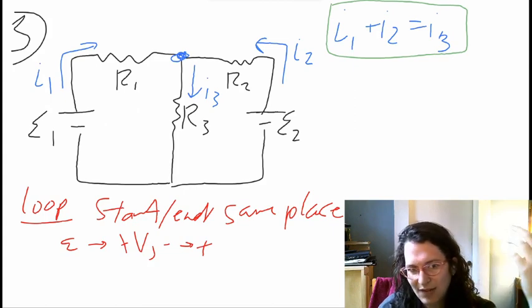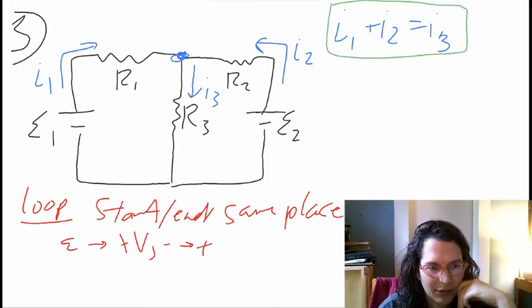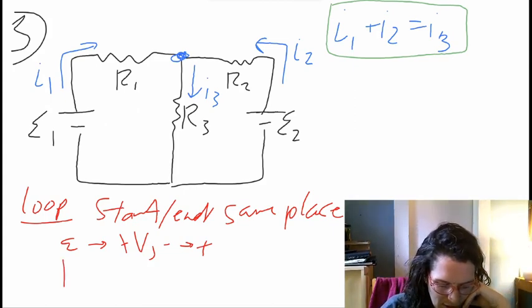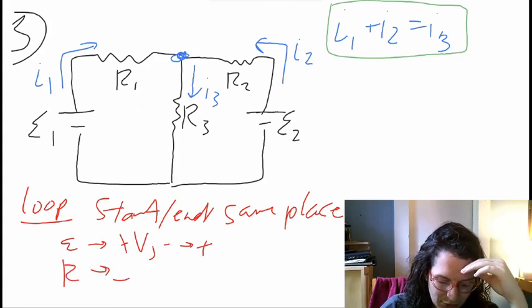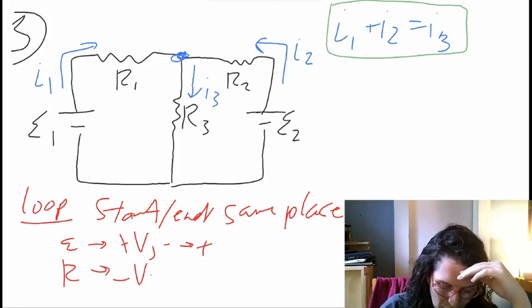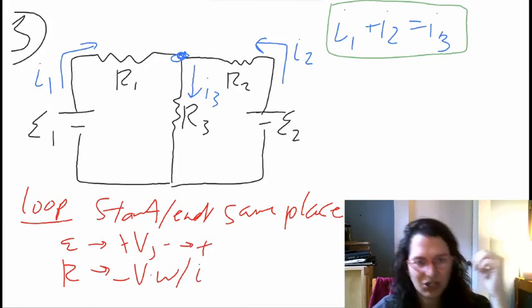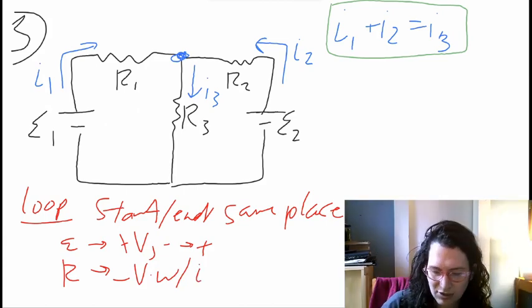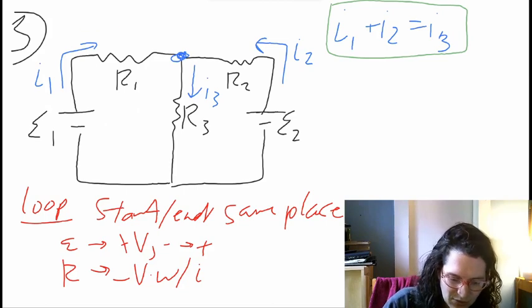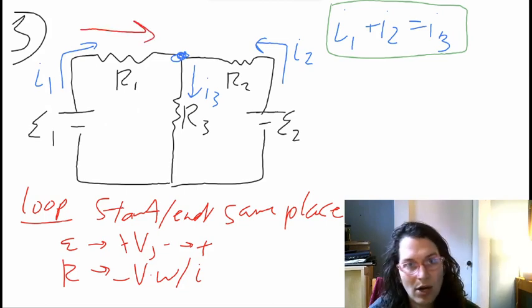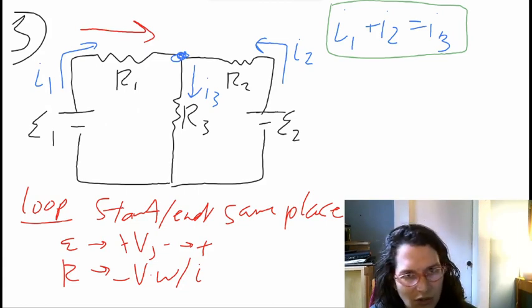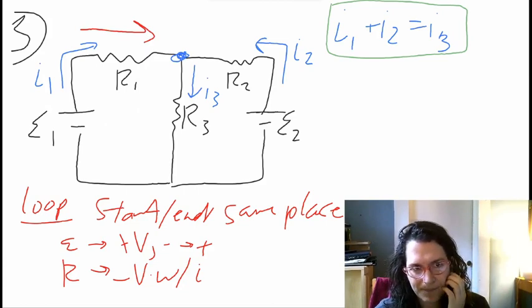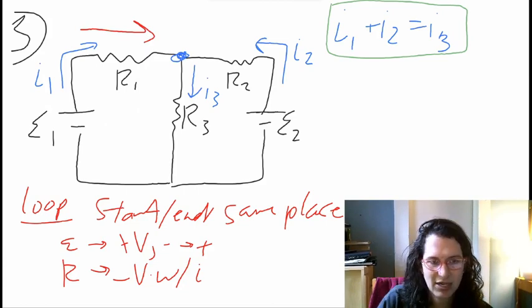And we subtract voltage when going from positive terminal to negative terminal. And then for resistors, we subtract voltage when going with the assigned direction or the assumed direction of the current. So as we did previously in the last problem, for instance, when we're going in this direction over resistor R1, we will subtract the voltage of resistor R1, which is I1 R1 in this case.